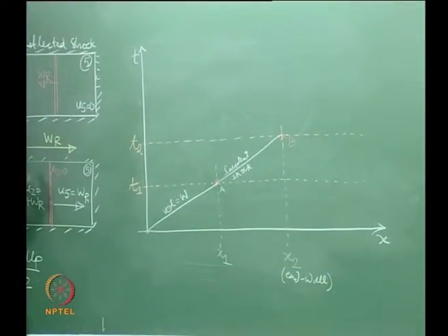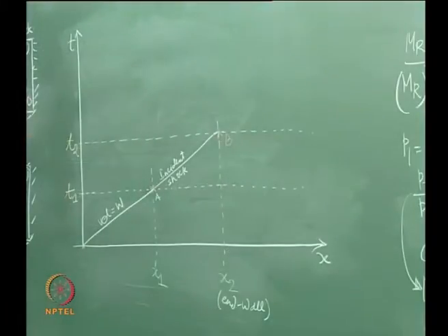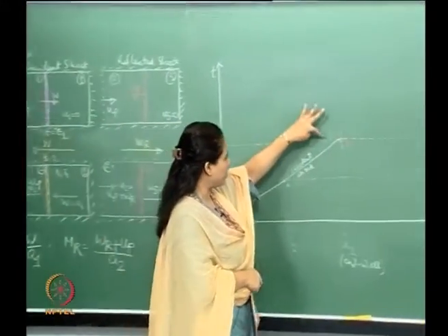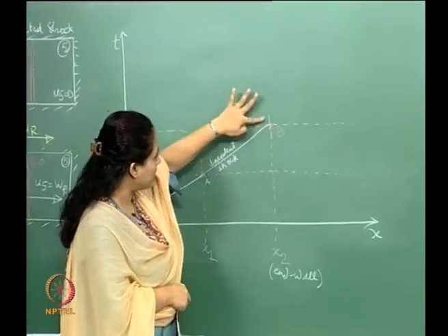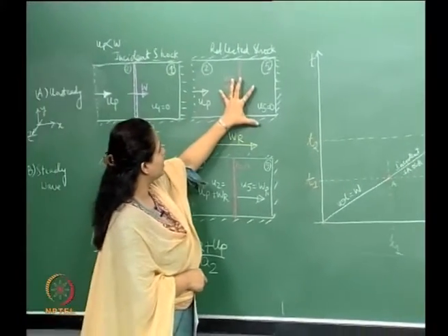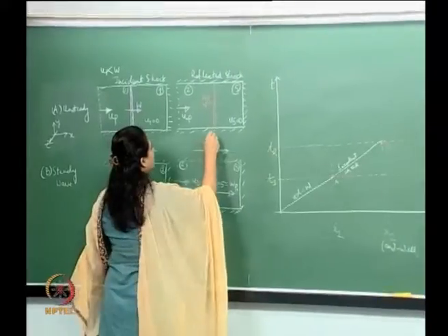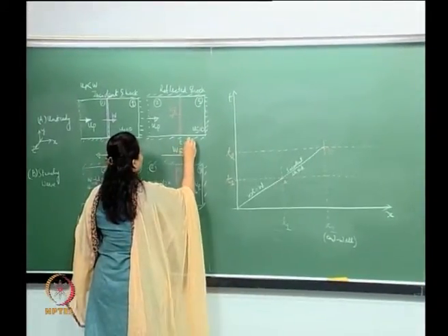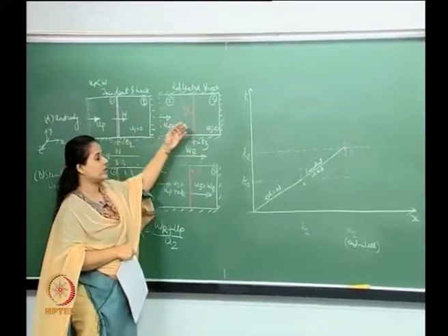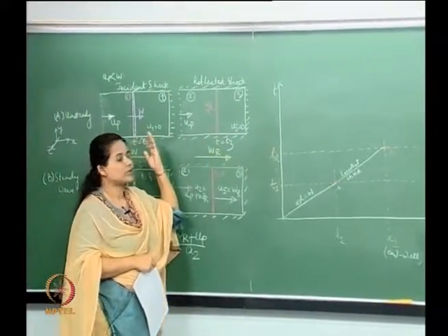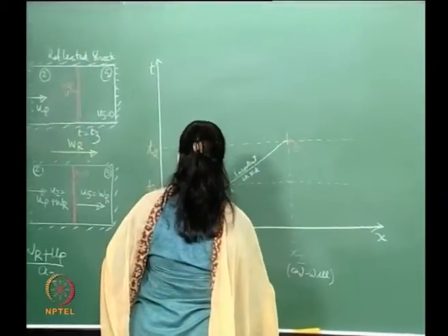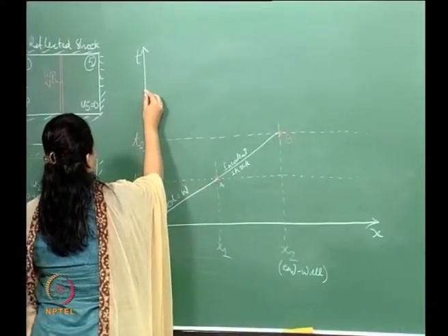Now after this, what happens is that there is the reflected shock. Okay. So the picture that we see here, at this point there is no reflected shock, but the moment it hits this, immediately after that there is the reflected shock, and this is what we are seeing at, say, time t is equal to t3. The picture that we see here is at t3, when the reflected shock has again traveled some distance. Okay. So now let us say at time t3,